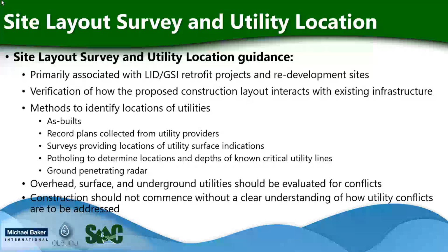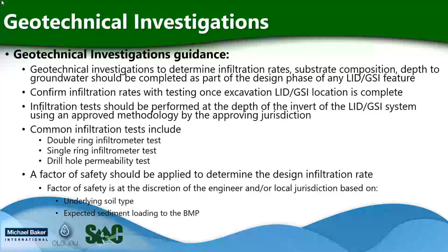The next element is geotechnical investigations. Accurate geotechnical investigations to understand infiltration rates are critical to those LID and GSI measures relying upon infiltration. Geotechnical investigations to determine infiltration rates, substrate composition, and depth to groundwater should be completed as part of the design phase of any LID and GSI feature.